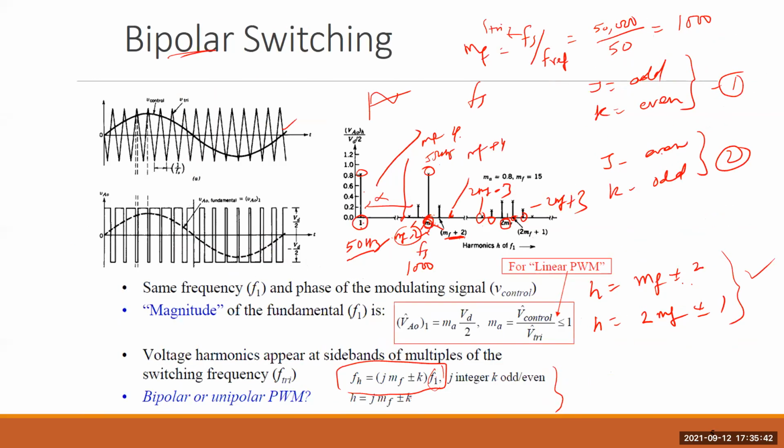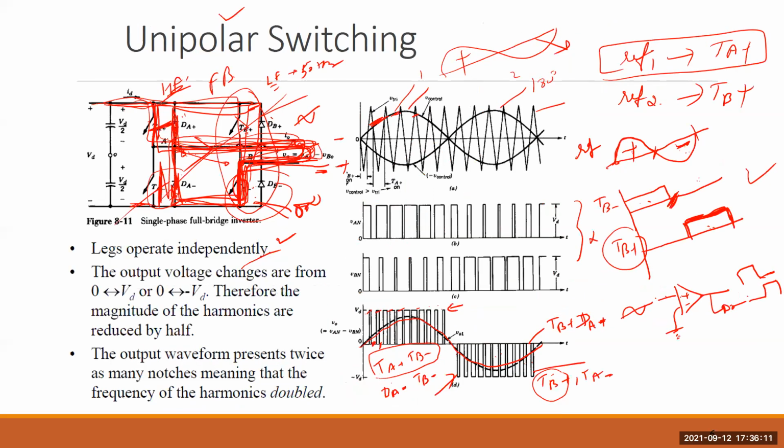So this way we can say that bipolar is more towards injecting reactive power compared to unipolar. But this is not a general statement. Suppose, for example, a fan kind of load. A fan is an inductive load. In any case, you need reactive power and you have to supply it, so that can be done by unipolar also. There is no restriction on this. It can also provide the same reactive power.